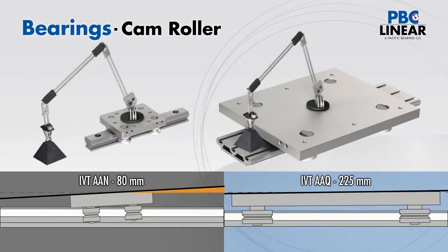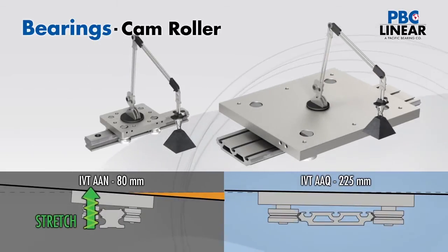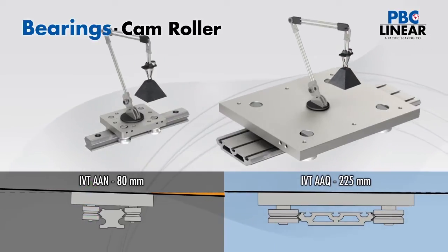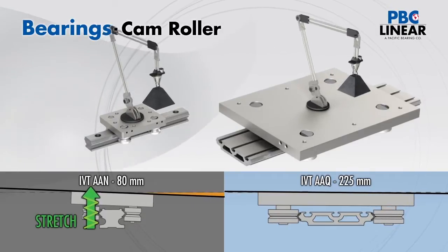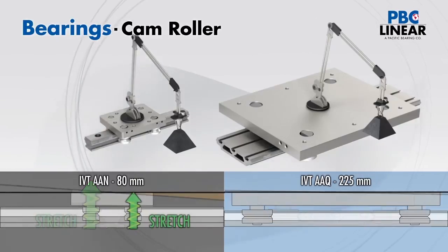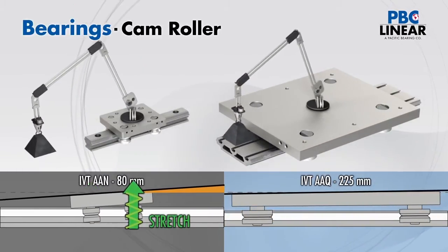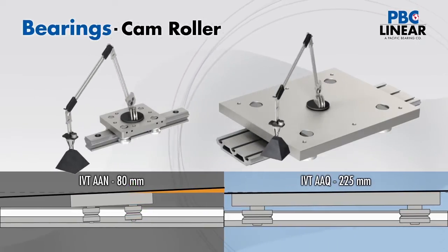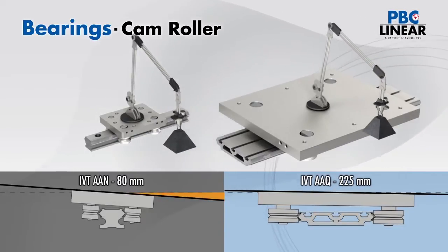Note that the wider spread of bearings, along with the ability to adjust for optimal preload with the eccentric roller, results in minimized deflection, stretch, and compression of the bearing studs, raceways, and fasteners, translating to increased repeatable accuracy at the point of interest. Remember that no bearing is infinitely stiff. There will always be some give in the material or deflection that will cause loss of precision.